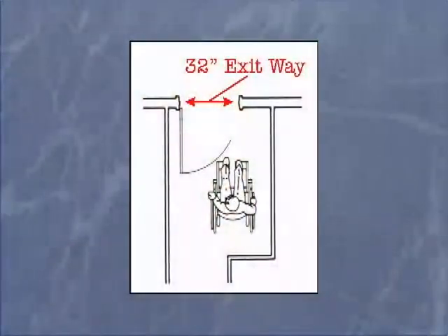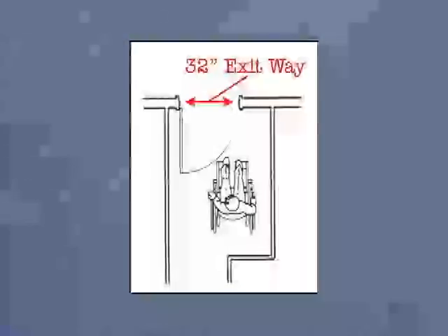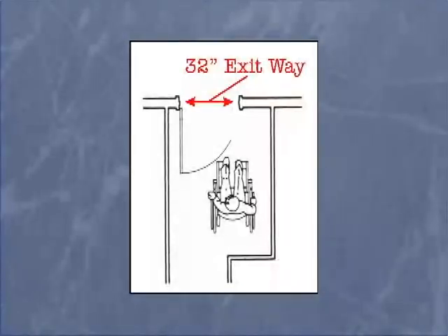Now, exit doors must be capable of opening a full 90 degrees and must be mounted so that the minimum clear width of the exitway is 32 inches. Let's highlight that as well. Take a look at stairways, read over that, and that pretty much wraps up accessibility.